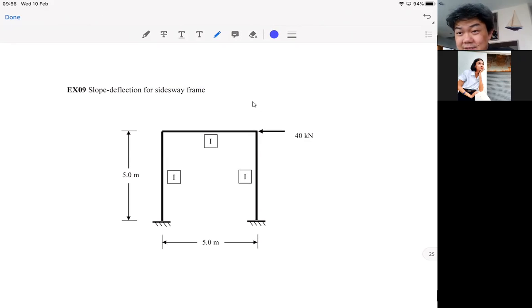And this case is pretty simple because we only have the load that will push your frame to the side, but we don't have any load to cause a fixed end moment. So without further ado, you now know that your frame is going to sway, and the sway is going to look like this. When you draw the picture, keep in mind that if this is fixed, the rotation is 0, so you must maintain it 0, and it goes to the side like this.